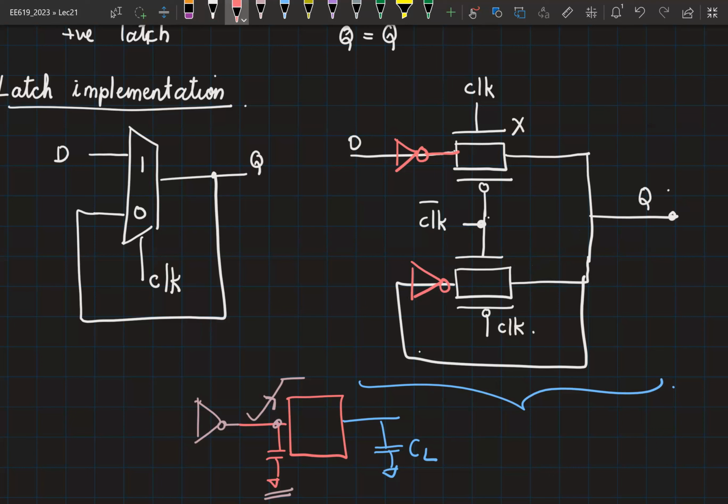So I'll come to that, right? But the drive strength including part, is it clear? It's either an inverter or a buffer, right? I include that here. So now the problem is, what is the direction of the feedback in this path? So find the direction of the feedback. I break the loop here. If I increase the voltage at this node, the voltage at this node also increases. What happens to the voltage at this node? This will also increase. So if clock is equal to 0, you have a positive feedback here, right?